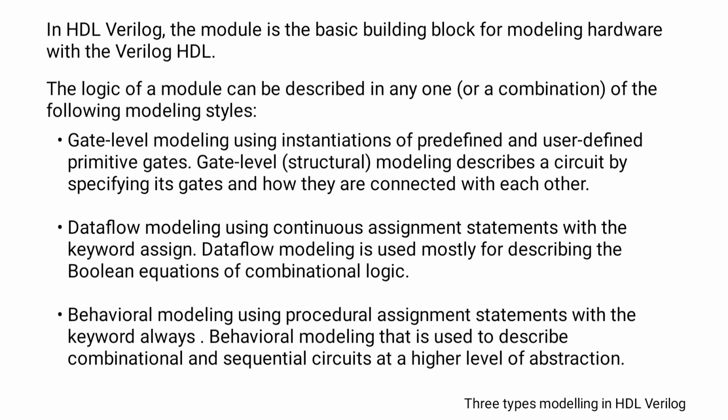The second modeling is data flow modeling. It uses continuous assignment statements with the keyword assign. In data flow modeling, we need not know the circuit diagram. We should know the logical equation that represents that circuit diagram. Data flow modeling is used mostly for describing the Boolean equations of combinational logic. To implement these Boolean equations, the assign keyword is used.